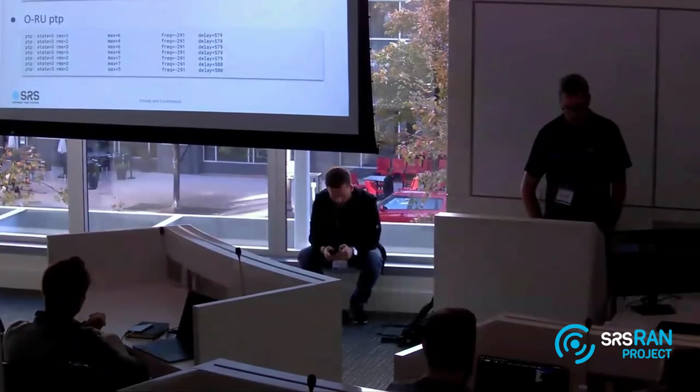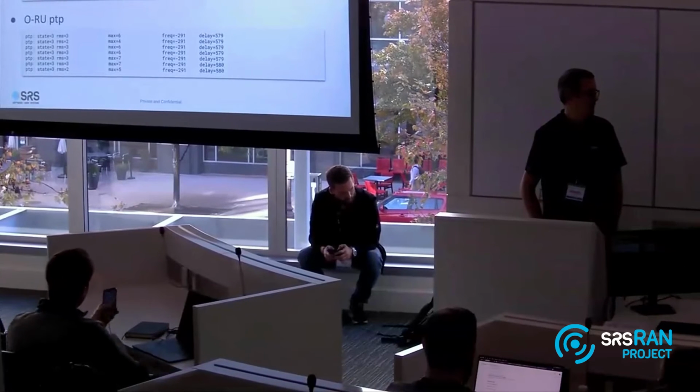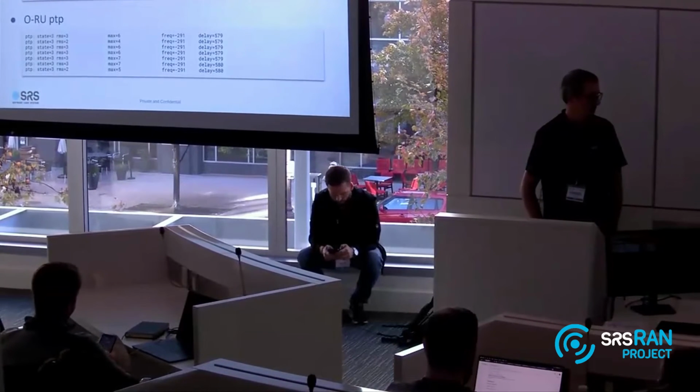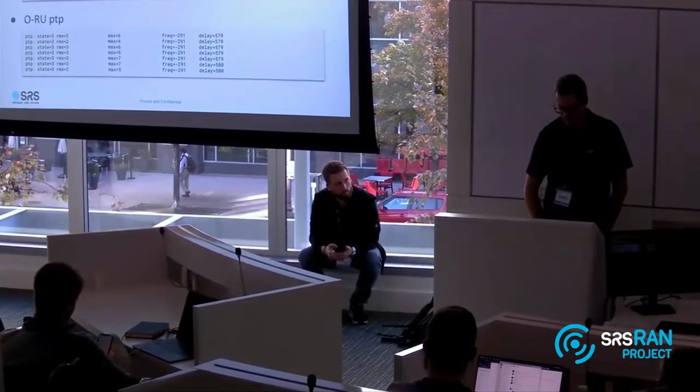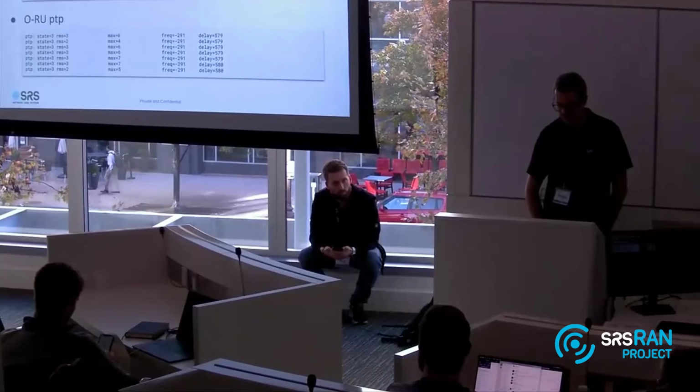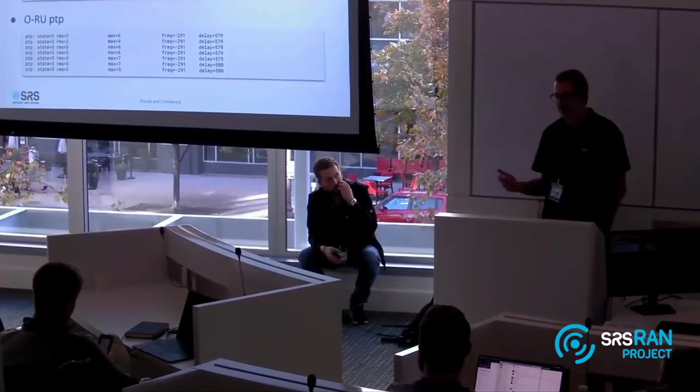What you want to see here, Borja, is values below 100, I think, no? Ideally below 20. You want to look at the RMS and make sure that the value is below 20. If the value is very high or it's oscillating between a high and low value, it means that something is not good on the PTP side, and this will mean that you will lose packets, or that the synchronization will not be good.